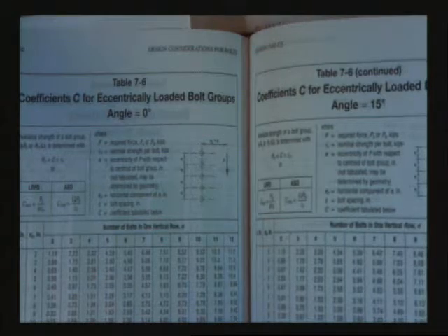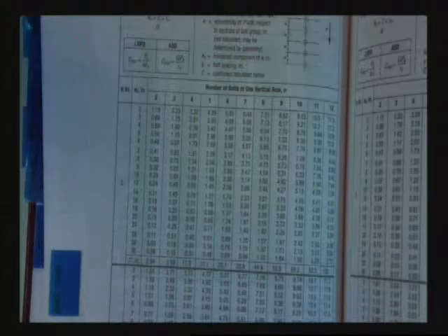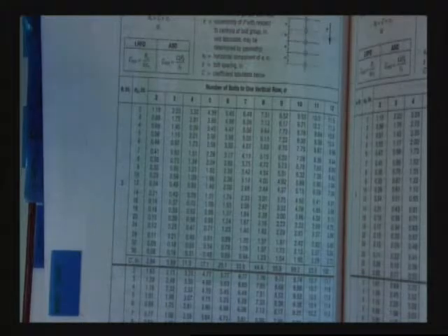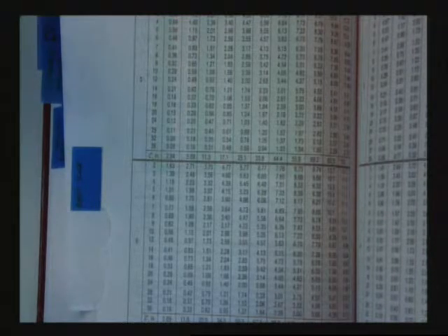What do you do if we have a spacing or an eccentricity or a number of bolts in a row that are not in the table? What do you do? Well, if it's in between values in the table, you can interpolate. Let's say it's greater. Let's say I use a spacing of 10 inches between bolts instead of 6. What's that? Redesign. That's a very good idea. If that's not allowed, then you better get your spreadsheets out. You better start guessing instantaneous centers, right? Looking at internal moments versus your external moments, and keep guessing and checking. But redesign's a better answer, probably. All right?